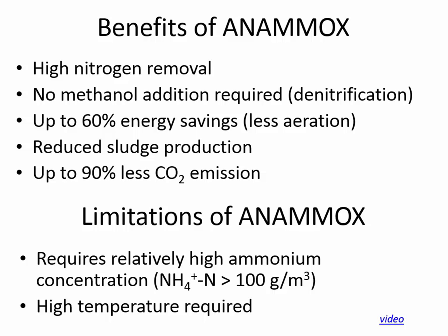The concentration of ammonium has to be above 100 grams per cubic meter, and that's very rarely going to be found in raw municipal wastewater, so it's not really feasible to use it there. The places it's been used in the past include a potato processing factory and a plant that makes yeast for baking.